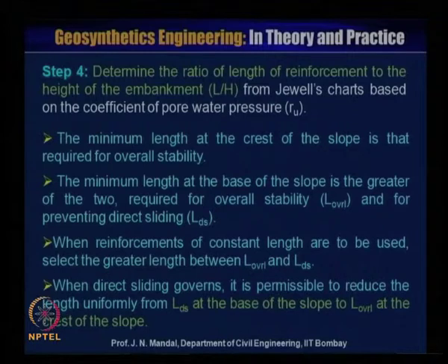So, whether the Ru value is 0, 0.25 or 0.50, accordingly from the design chart you can calculate the length to height ratio of the embankment.